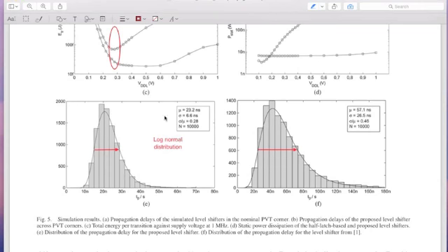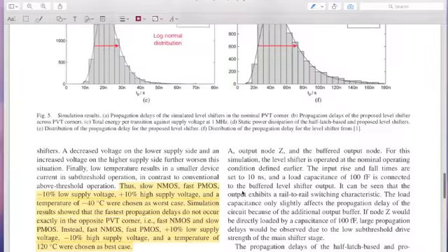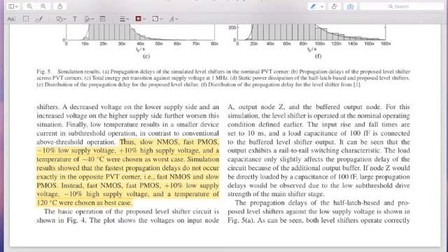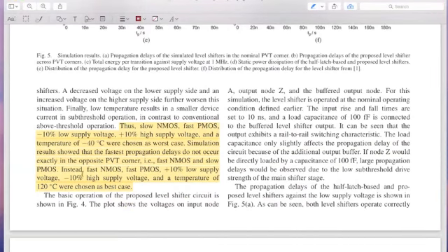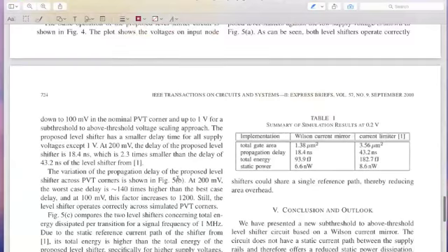So they compare their approach versus the previous approach and essentially see how well it works. So this is where, again, how they compare. The worst case condition is slow NMOS, fast PMOS, VDD low side is made lower, VDD high side is made higher than nominal, and use a low temperature. And they use a temperature of minus 40 degrees. Okay, their circuit is supposed to run from minus 40 to plus 125. So military grade operation, you have to use these larger spreads.